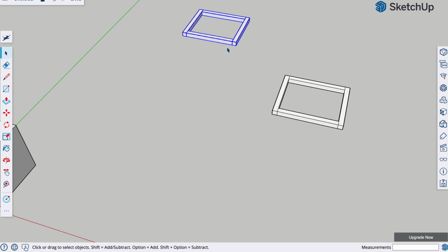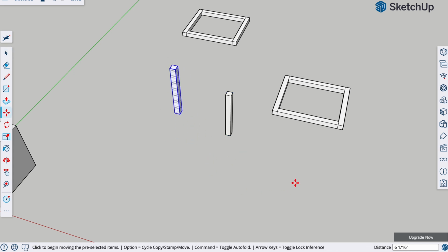We know the top frame is also going to be 1 inch, so our vertical beams only need to be 10 inches. So go ahead and hit R, drag it out to 1 by 1 inch, hit P, drag it up, type 10. Great, we have a 10-inch beam, triple click it, and then we know we need 4. So we're Control C, Control V 4 times. Draw the 4th one here. Control C, Control V. All right, so we have all the components of our bench.